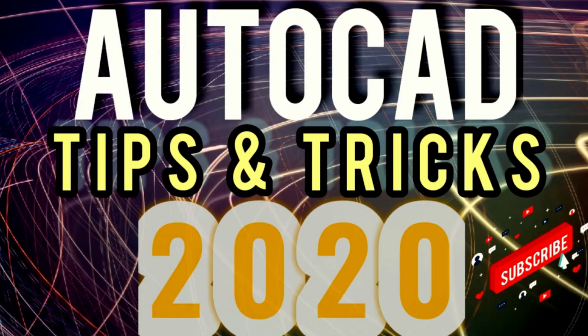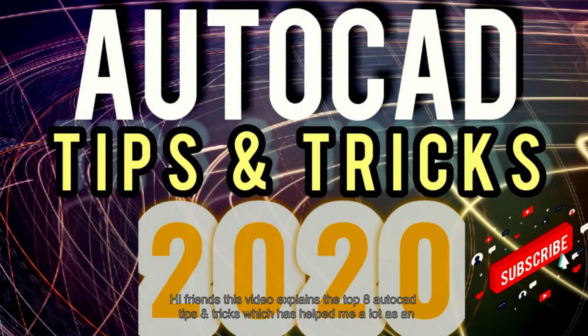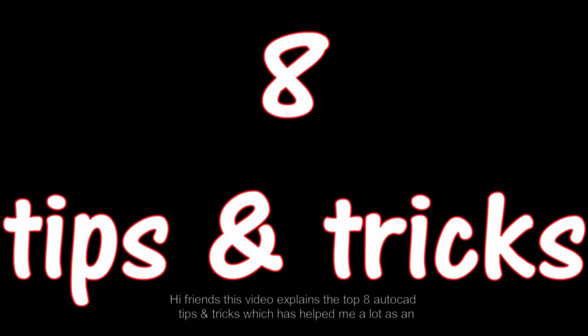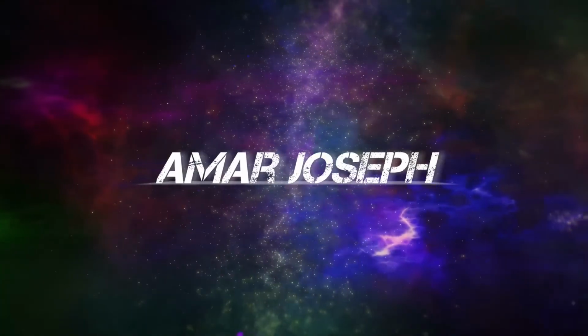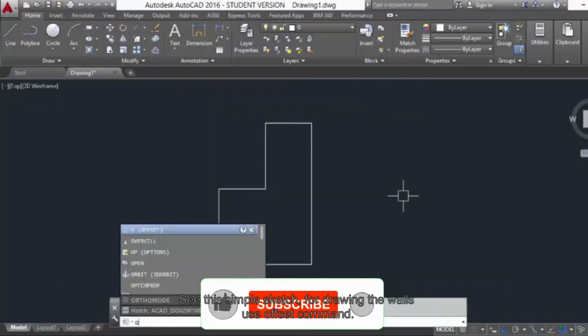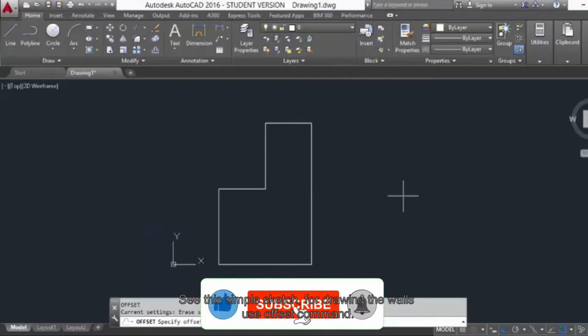Hi friends, this video explains the top 8 AutoCAD tips and tricks which has helped me a lot as an AutoCAD designer by increasing my speed and productivity. See this simple sketch. For drawing the walls, use offset command.